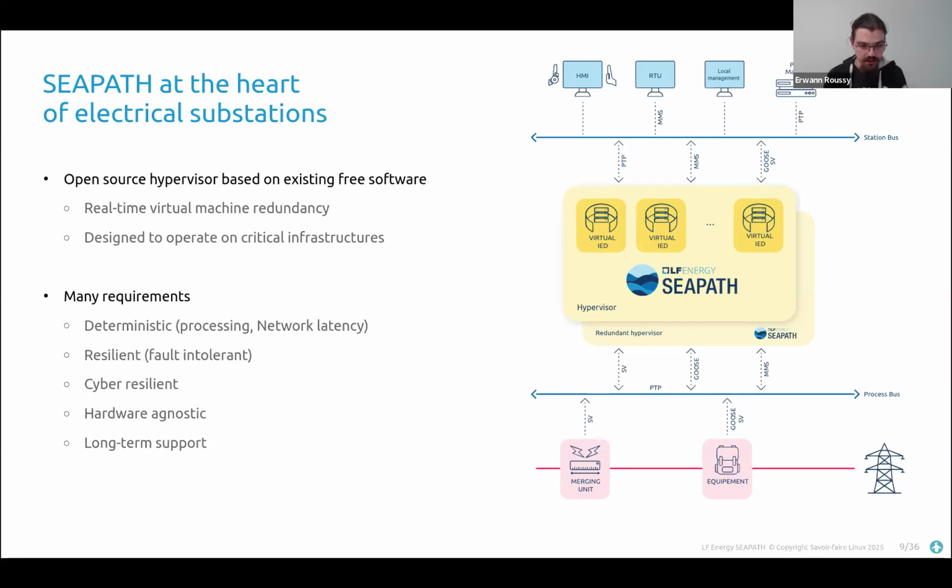Today, what we are doing in the SEAPATH project concretely is that we are also going into the containerization question. For those who don't know the container world, let's think about it as very tiny virtual machines with less isolation, and it costs less RAM and less CPU and all of that. And we are investigating that today. We are running containers on SEAPATH. The idea would be maybe that DSOs and the smaller substations run SEAPATH with containerization instead of virtualization.